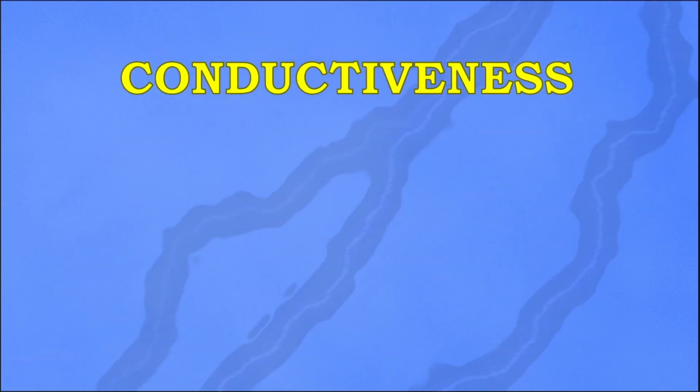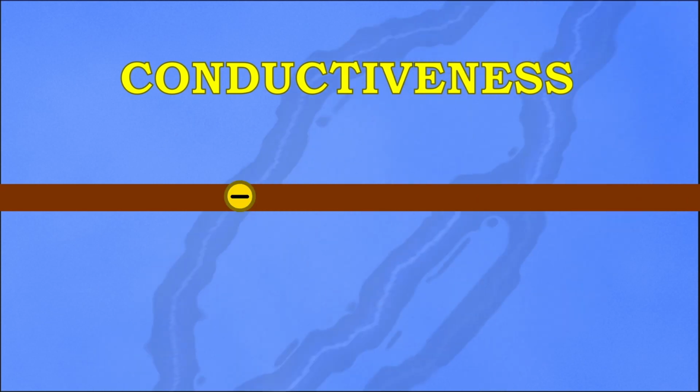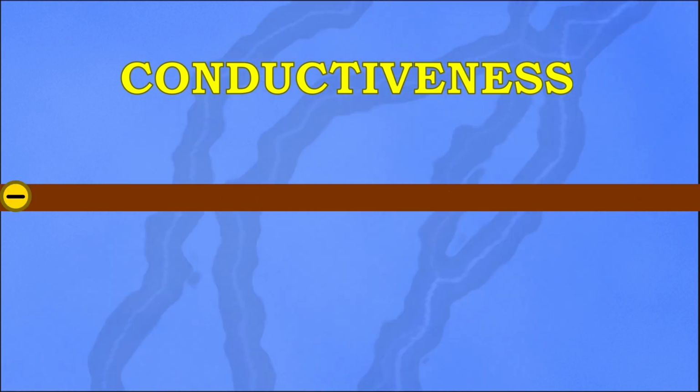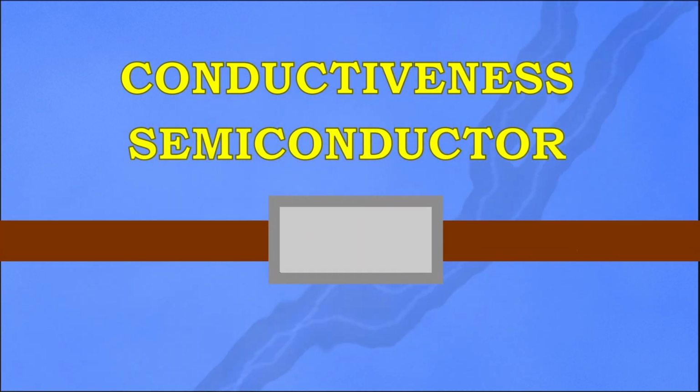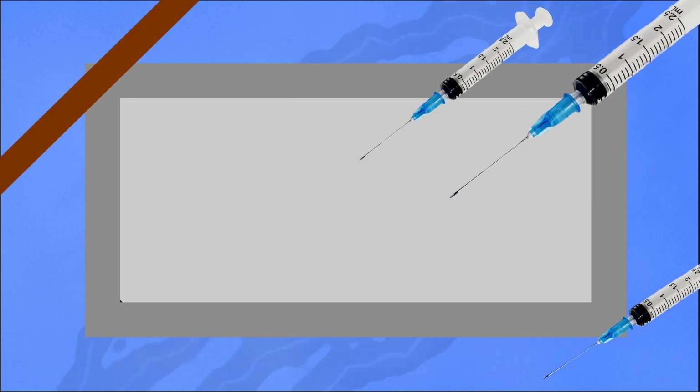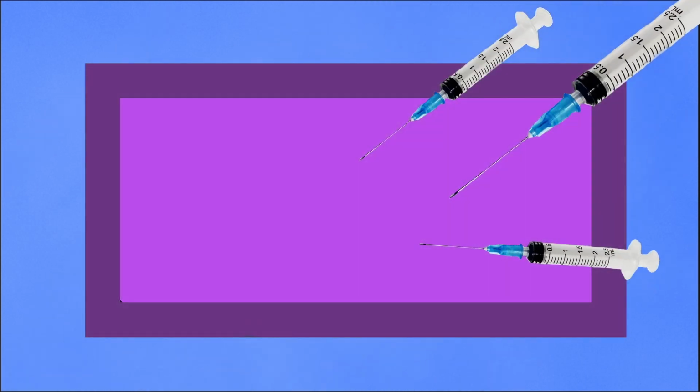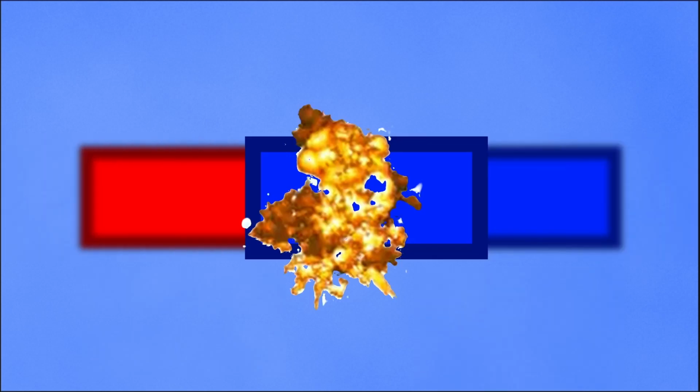Basically, there are 3 kinds of materials in terms of electric conductivity. There are conductors that conduct current when a power source is connected to them, there are insulators, they block current, and there are semiconductors. They are in between the two, not being fully conductive nor fully insulative. So to make them closer to conductors, we dope them with certain materials that improve their conductance. There are 2 types of semiconductors, p-types and n-types. The way we dope semiconductors is by fusing them with other materials.